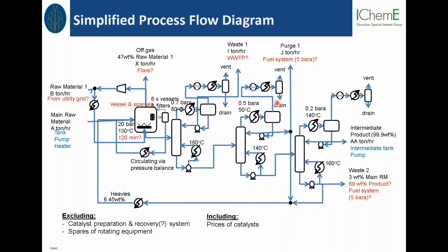So you can see now here all these red things, the ones that we don't know. For example, in this reactor, if you look deeper, I put in some numbers. It says, from the literature review or from the batch reaction experimental results that our chemists have done in the lab, that they need 120 minutes. Then as a process engineer, we should ask ourselves, do we really need this 120 minutes? Can I see your data on conversion and selectivity in terms of the operating conditions? These are the questions that we can ask or poke our chemist colleagues with.